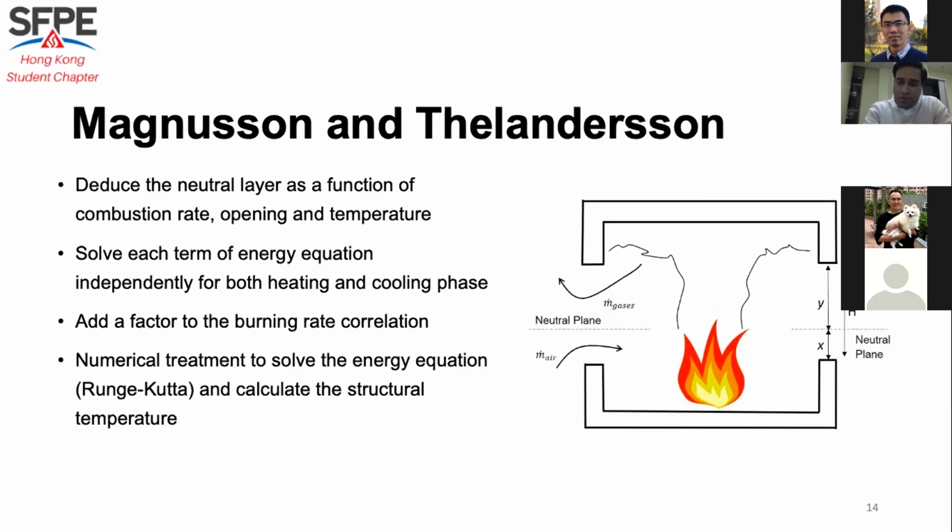They provided this factor and were able to introduce new equations for the burning rate for all phases, the cooling phase as well as the heating phase. Then the whole set of equations was solved numerically using the Runge-Kutta method to calculate the structural temperature. So this was also one very important work for structural engineers. Whoever is working in structural engineering, I would suggest going through their work as well.